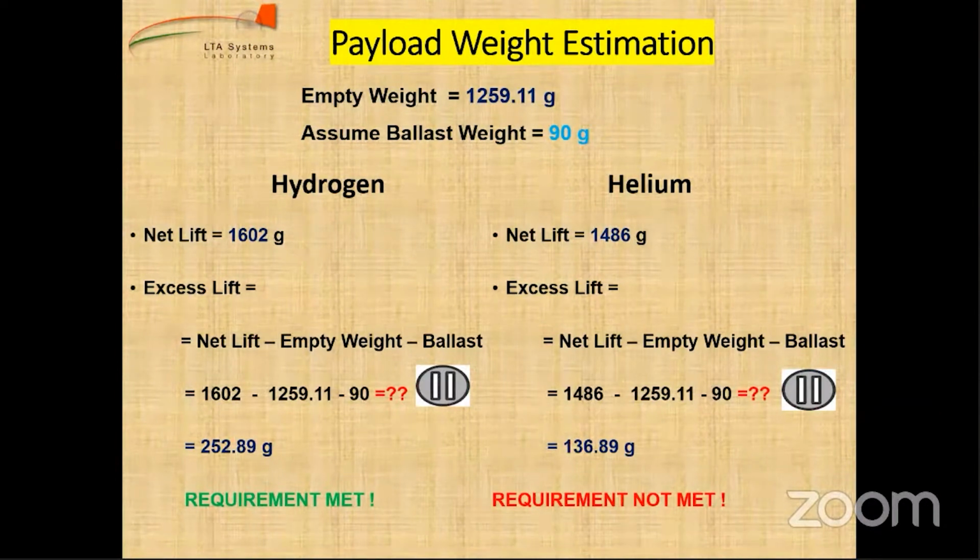So you have to keep a margin in the variability. So therefore, for example, now we are getting exactly to 52.89 kilograms payload. I think this is going to be very risky, because you will build the whole airship and you find that there is some problem. So I understand your constraint, but that happens mostly when you go for non-standard equipment. When you go for standard equipment, then you do not see so much of variability.